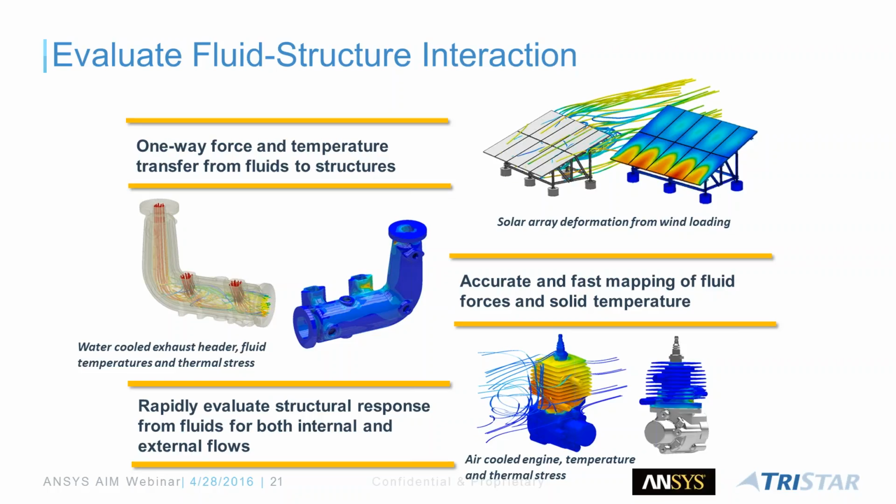However, I'm also interested in capturing that pressure distribution or the force on the geometry and running a structural analysis and seeing if it's going to fail, what is the maximum deflection, and what is the stress based on the yield, etc. So this is a good example where you would need multi-physics to work, or you need to couple them, and the fluid structure interaction template allows you to do that. And it could be the thermal also, right? To air cool, just simulation on that cooling fins on an engine.